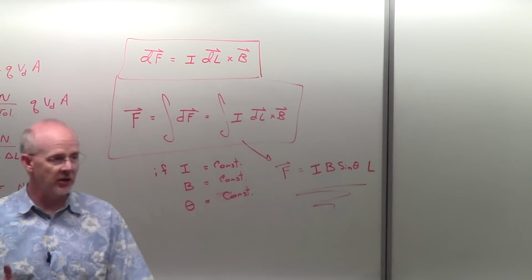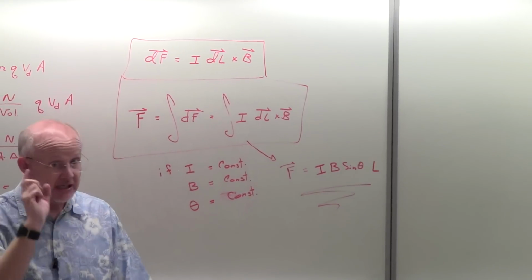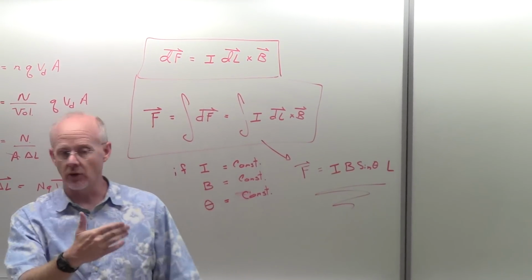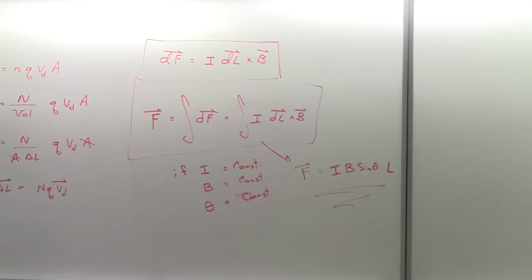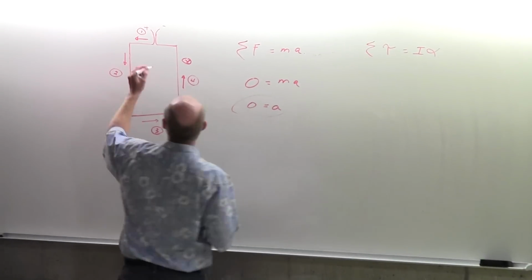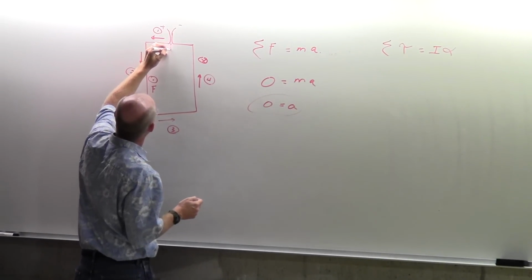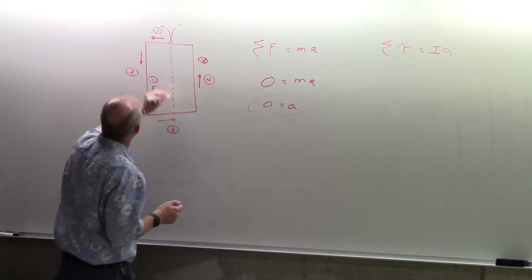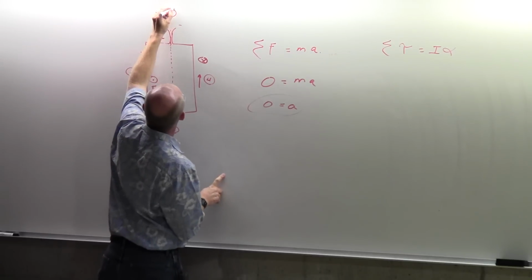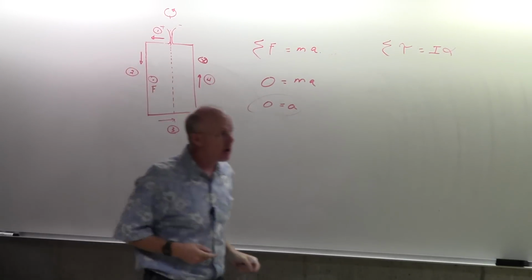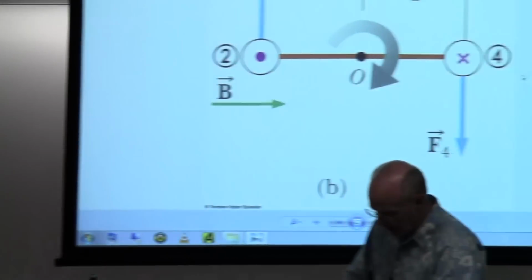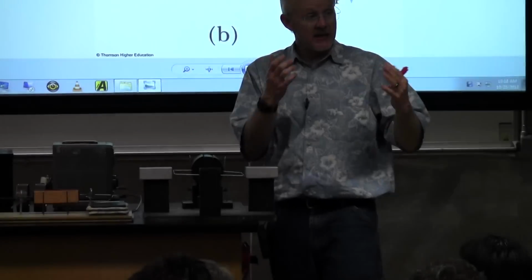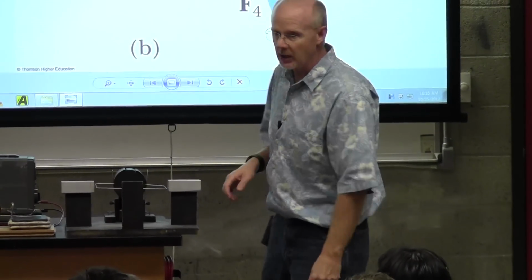I looked at the forces and realized this thing's not going to translate. But in a second, I'll realize there is a net torque, which means it's going to rotate. And so it does have a rotation. So I would look at it, and in this case, it is designed so that the wire has the ability to rotate around an axis down the center, as you can hopefully see in this design here, is it can spin. And it can spin if there is a net torque on it.